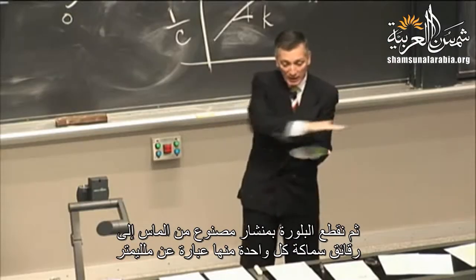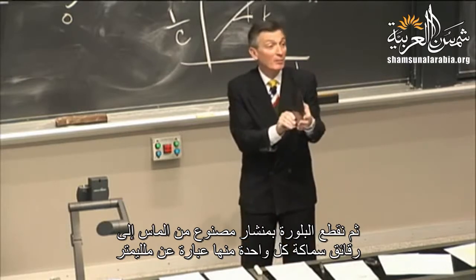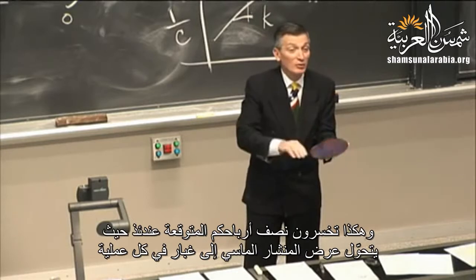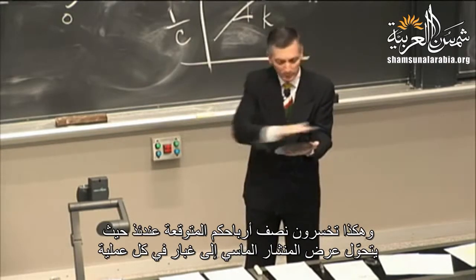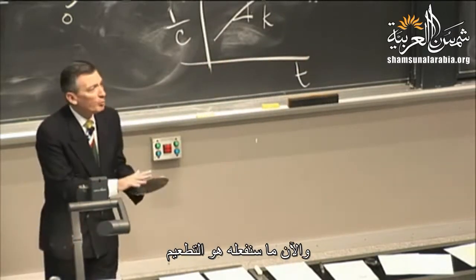And then we take this and we cut it with a diamond saw into wafers, each of them about 1 millimeter in thickness. And of course, the width of the saw turns into dust. So your yield right off the bat is about 50% because it's all gone. All right? And now what we're going to do is we want to dope it.